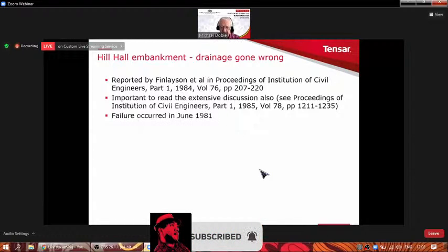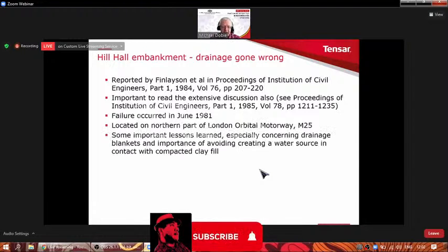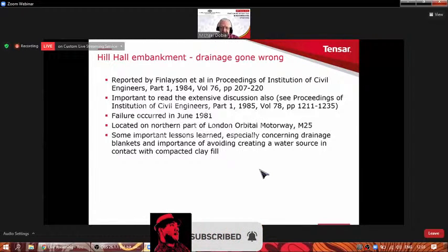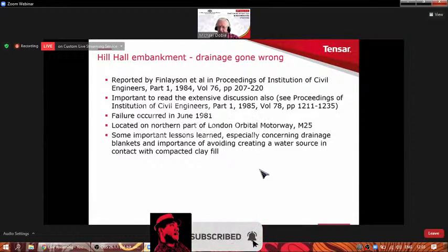The failure occurred in June of 1981. I've already mentioned it was on the M25. And there, without a doubt, there were some very important lessons learned, especially concerning drainage blankets and the importance of avoiding creating a water source in contact with a compacted clay fill. Just think about our friend Clay again, our packed clay. So let's have a look and see what happened.